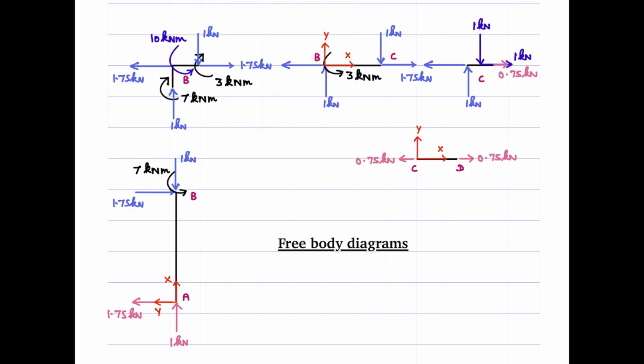Okay. So when we move from this to this portion, the same forces in the opposite sense are marked: 1, 1, right? 1.75, then 1.75. And then what else? Maybe I should have shown this here. Anyway, it doesn't matter much. And finally, this 7 is counterclockwise. This should be clockwise 7 kilonewton meter. And additionally, we have this externally applied concentrated moment.